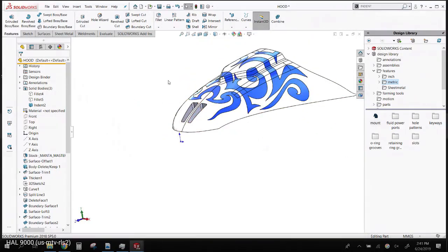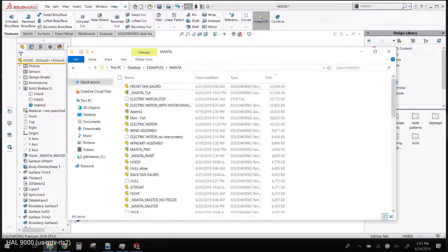When you start getting into this, this is why we got some files that are pretty darn big. Here's my top level assembly. I've got a part file in that top level assembly that takes up more RAM than the assembly itself. This is where you have to start thinking about what exactly is in a SolidWorks file. So there's the header, there's the feature manager tree information, there's the parametrics, all the numbers that you typed in there. That's actually a very small amount of data. Most of the data in a part is your graphics. I've talked about it a bunch of times.